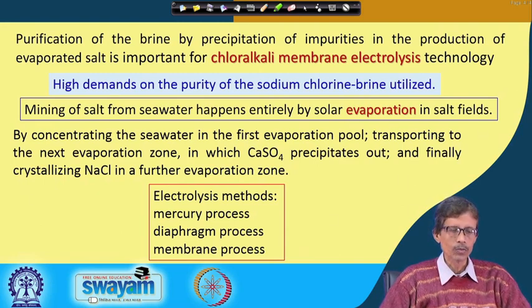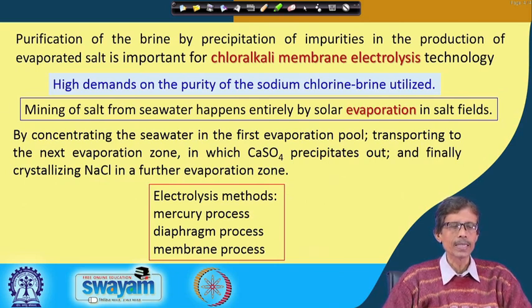So, first, let us consider the mercury process. Why do we use mercury? We know that mercury itself can be an electrode, and it can be in liquid form, because we know that mercury can serve as a good cathode in the electrolytic chamber during electrolysis. So, with a mercury pool, we also know, as we have seen somewhere, that sodium amalgam can be helpful, if in the presence of mercury some amount of sodium amalgam is formed over the surface. So, we will have a mercury process.